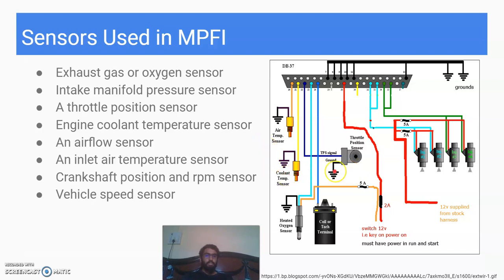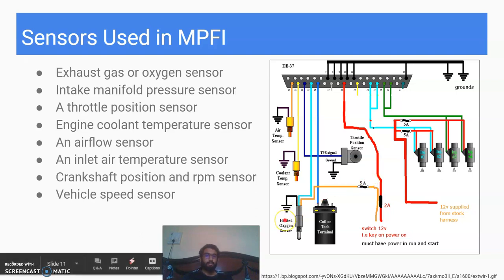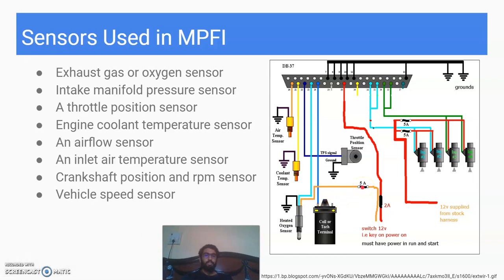The engine ignition signal sensor analyzes the signal and a spark is produced at the correct timing. Then the pressure of oxygen in the exhaust gas is analyzed by the oxygen sensor and signals are sent to the ECU. The amount of air-fuel mixture is controlled by the ECU through the throttle position sensor and air intake sensor. So this results in better fuel injection.